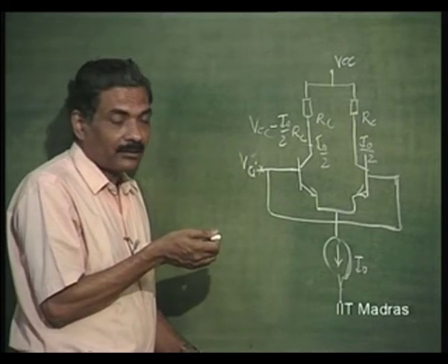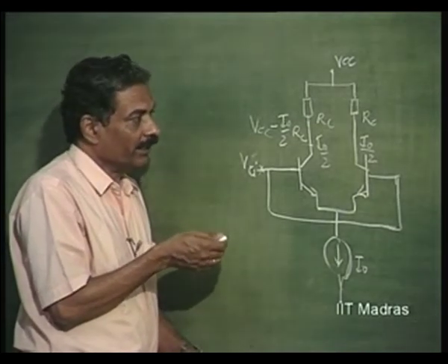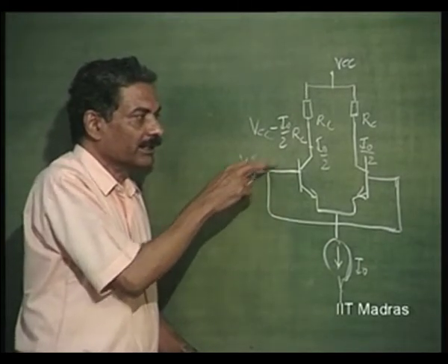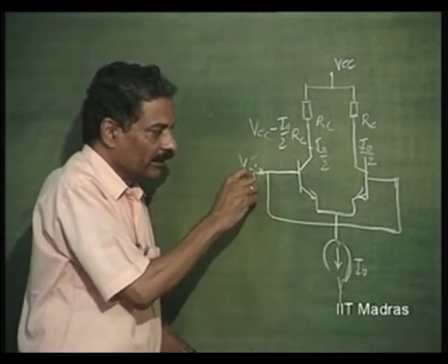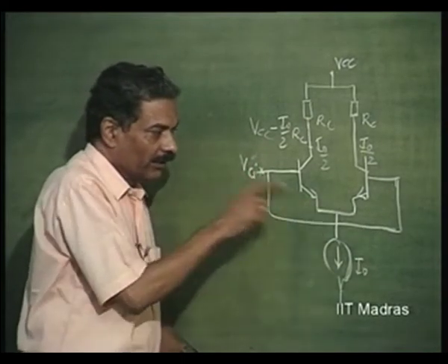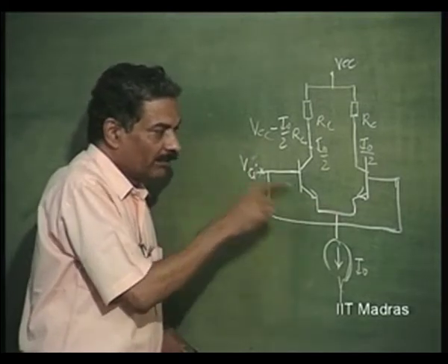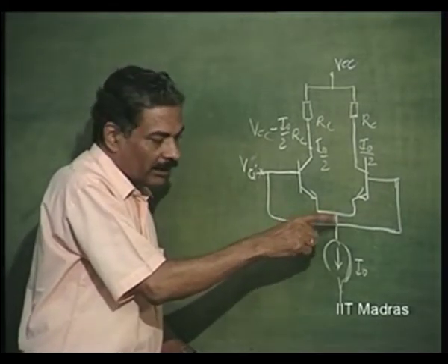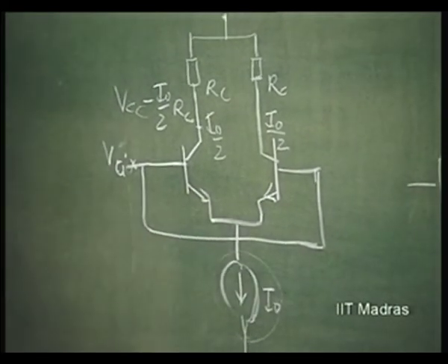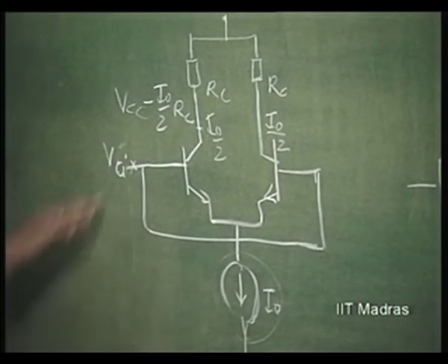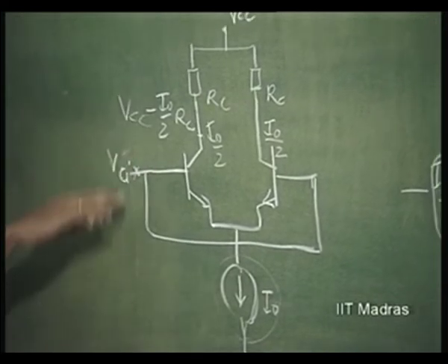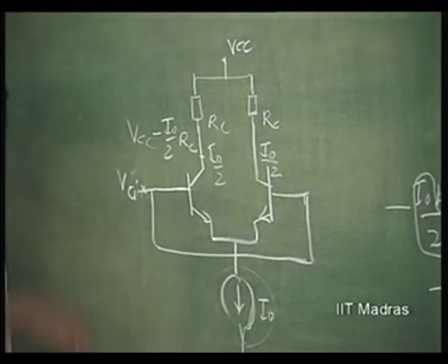Right. So, this kind of thing can be prevented if you take care to see that this common mode voltage does not exceed this. On the other side, this voltage can go down and this voltage will follow this, Vc minus V gamma will be the voltage here, and at that time this current source should remain still active. So, that is the condition. So, there is a limit on Vc max as well as Vc minimum as far as the input stage is concerned.